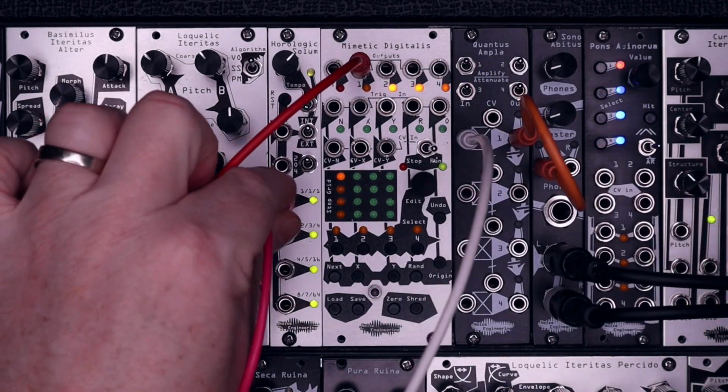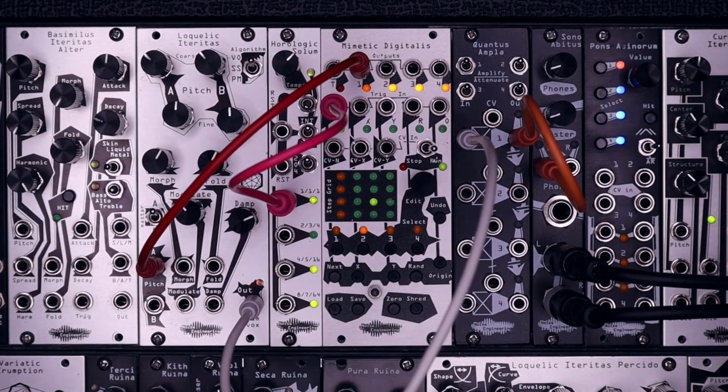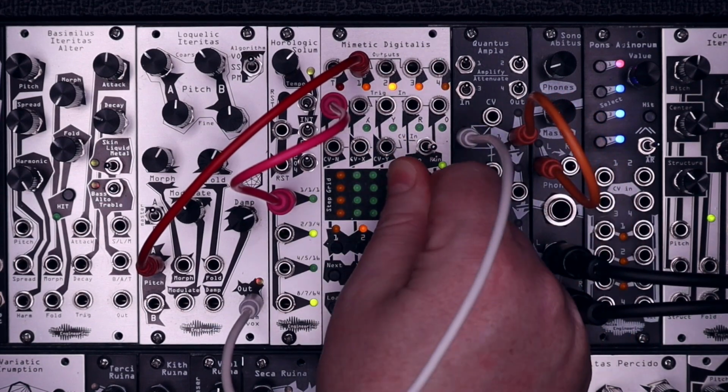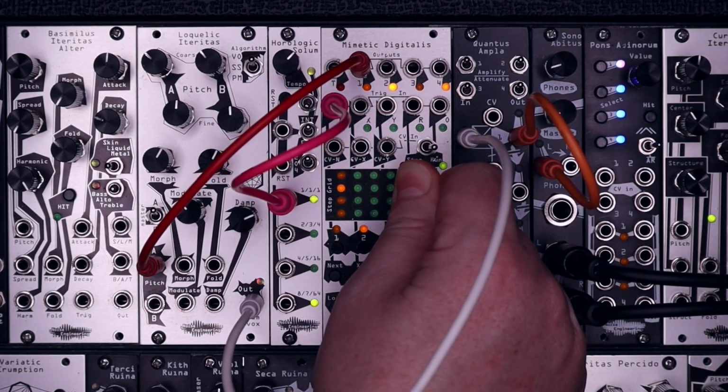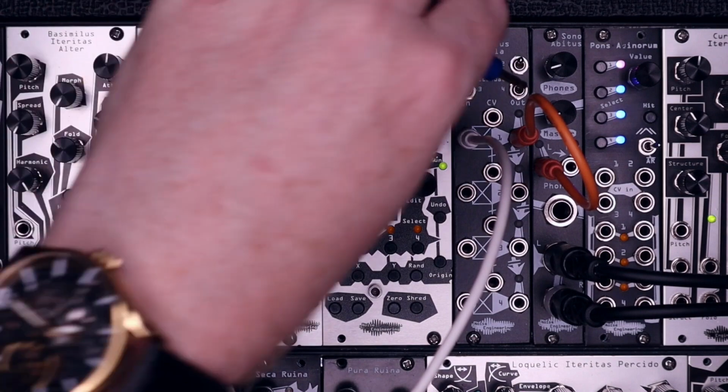Add your clock to the MD, select the second CV to edit, then push and turn the encoder clockwise until you reach the highest value. Keep it pushed down through an entire 16-step cycle. Patch that CV to the CV input on your VCA.